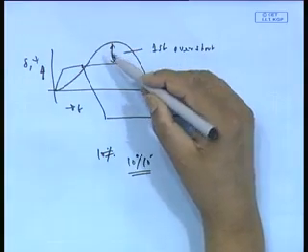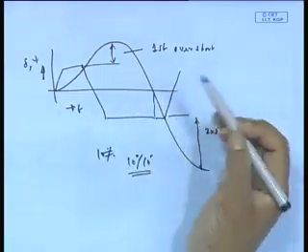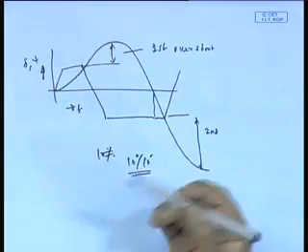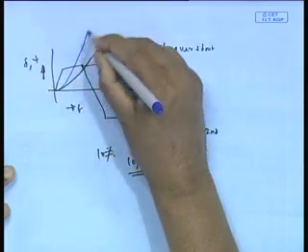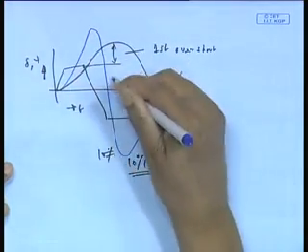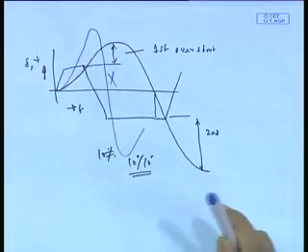Now you see why I am saying this. I told you in yesterday's class that if a ship is highly maneuverable, then it normally reaches faster but overshoots much more, and that is not accepted. So you cannot have a ship which goes overshooting like that. A ship which is highly maneuverable will try to turn very quickly, but you cannot have that beyond a certain limit. That is the stipulation.